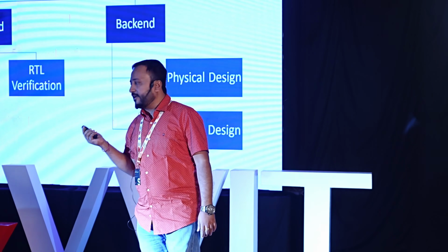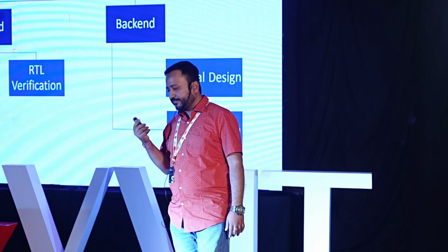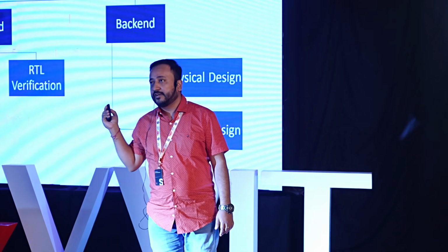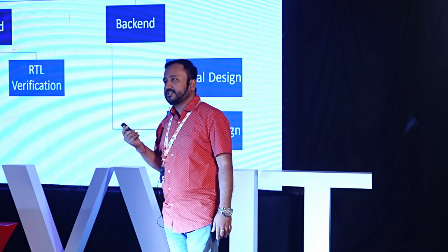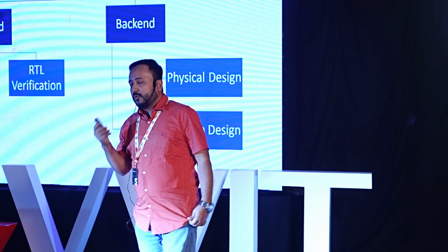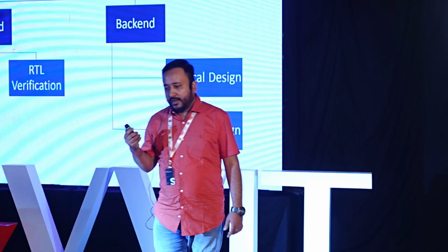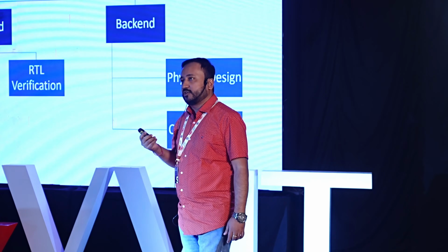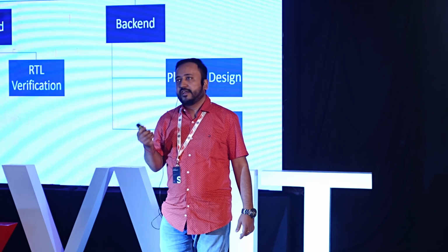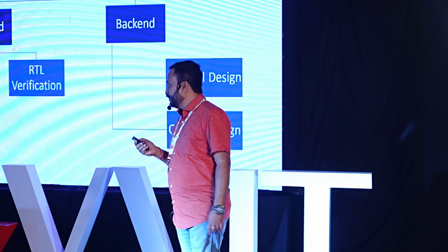So front end again is divided into two parts, the RTL design and the verification. RTL design is mostly related to the designing or modeling of the circuit, and the verification part confirms that the design is working as per the expected specification or standard. So one more thing I want to add here is that, as I earlier told, the number of transistors matters. Along with that, the type of transistor is also important. So that's why MOSFET is a preferred choice over bipolar junction transistor, and the reason is that the power consumption of such devices is very low.